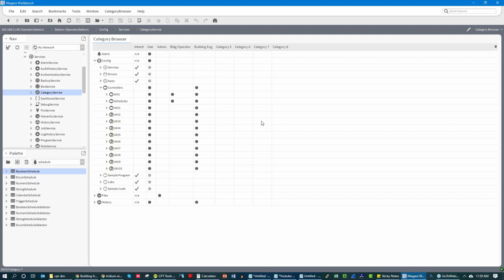This is something I see a lot of owners and operators get wrong, is they don't have this level of granularity, and then the maintenance guy goes in and accidentally deletes the discharge air pressure set points and shuts down air handlers or wipes out balancing values. I've seen it happen time and time again. And so it's important that we regulate what folks are able to control by going and setting up users and